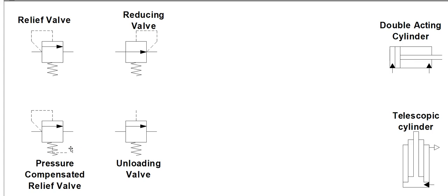What we mean by pressure compensated is that if we have a pilot pressure coming into this line, it would actually assist the spring and add on to the spring. So if this relief valve spring is set to, say, 1000 psi, and we have 500 psi of oil pressure coming in on this line, the inlet pressure of the valve would have to build up to 1500 psi before it could open up. Depending on the circuit, we might want to change the pressure at which this opens. So it's pressure compensated, meaning there is oil pressure coming from elsewhere to help out the spring.